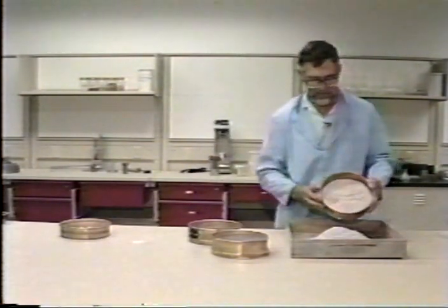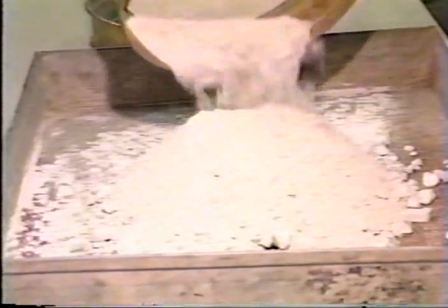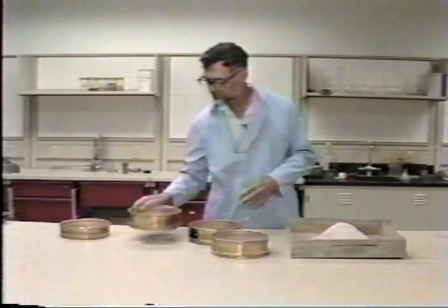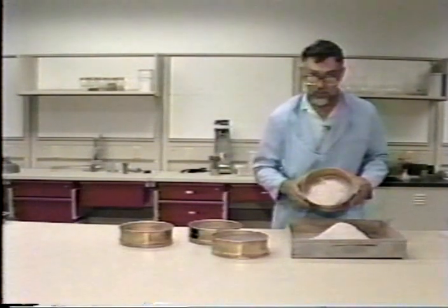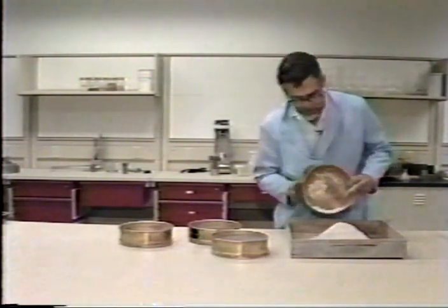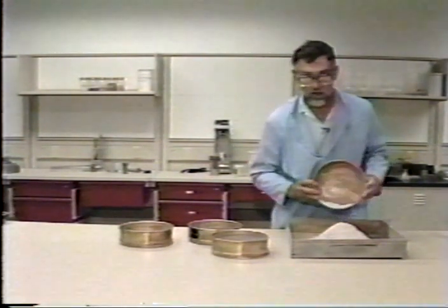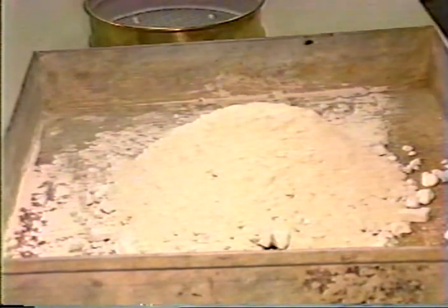Next, I'm going to place the sand-sized material, which is even finer, into the pan. Finally, I'm going to place what we call the fines, which is silt and clay, in, and you can see there's not very much of this material in the SB2 mix. SB2 specifications allow up to approximately 8% fines maximum, but it can go down to 0. And in this particular sample, there are very, very few fines.